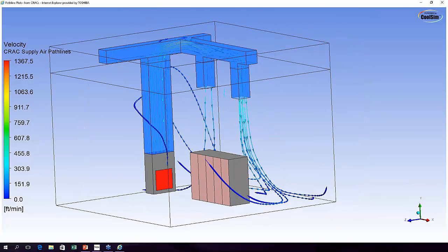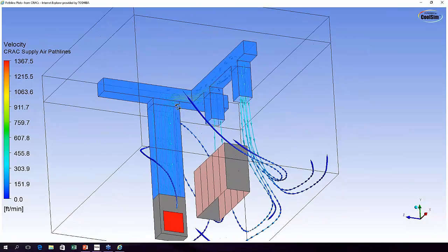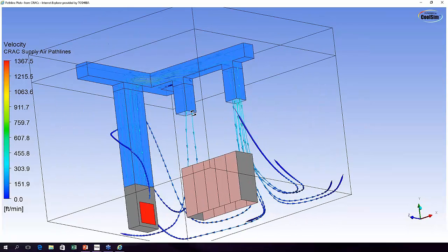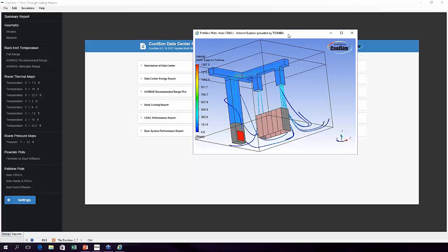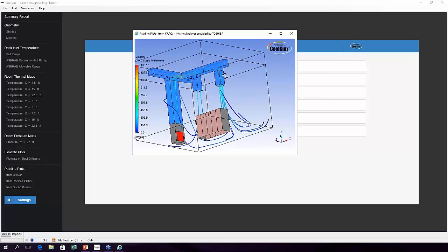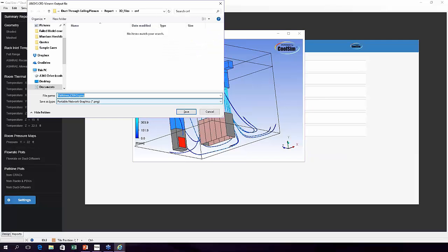But one of the things that you can do that's quite nice for generating reports is create a PNG of this image in any orientation you want, at any aspect ratio you want. So say, for example, right now I'm using full screen, so my aspect ratio is probably about 4:3. But if I was making a Word report, I may want it to be more like a 1:1 ratio, which is a little squarer, something more like that. When I hit the P key, P stands for print, it'll generate for me a PNG of that file.